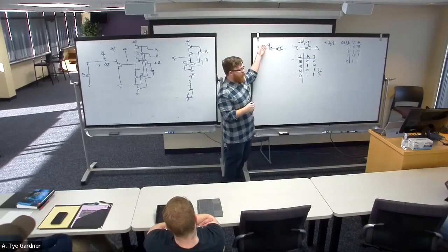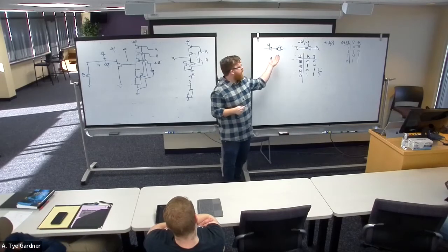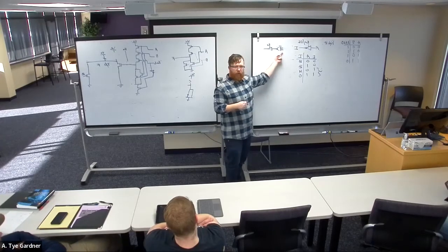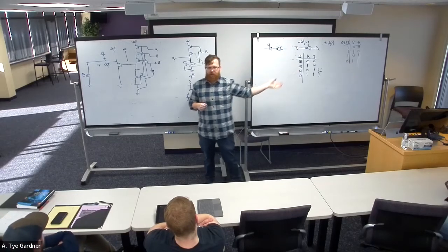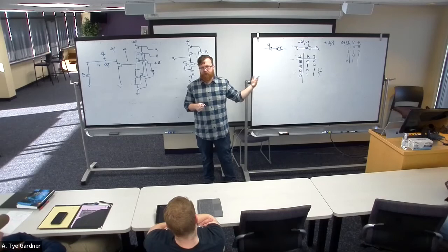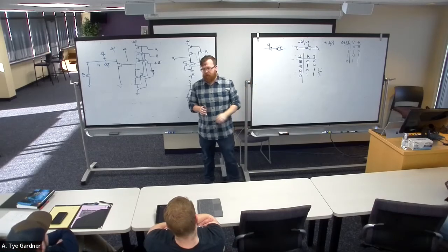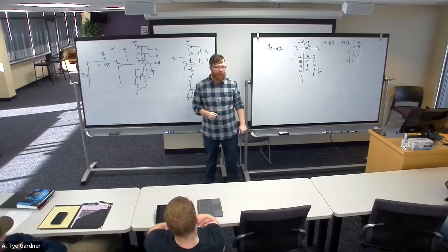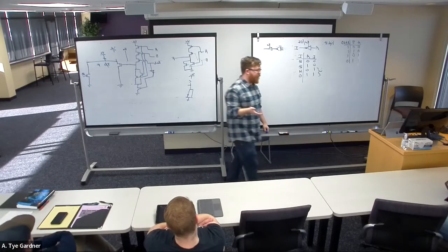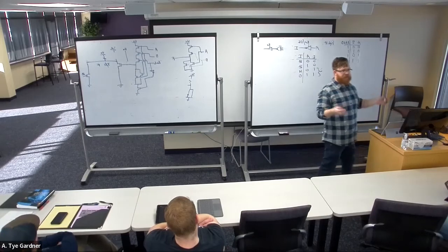And so this enable is a control signal, right? Data is flowing through, this is making decisions. The enable is a control, it is just saying either you're turned on or you're off. So control tends to be active low because the architecture lends itself to being that way. We'll see the same thing when we get to circuits that have memory, when they remember things.